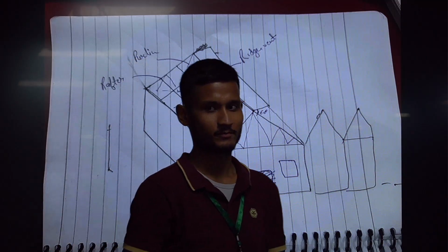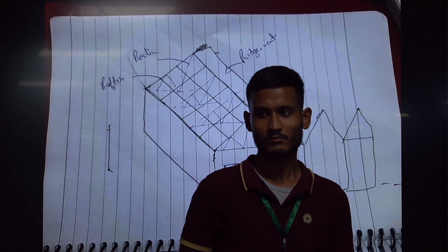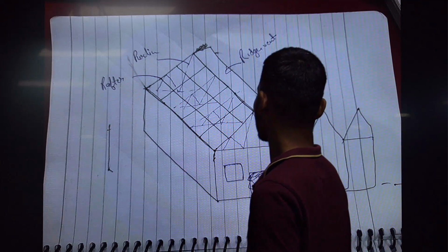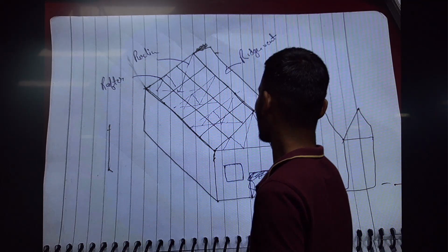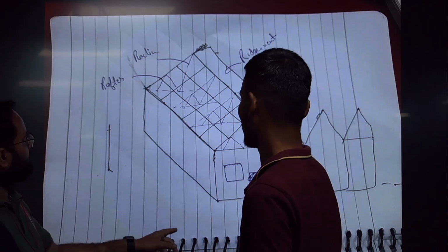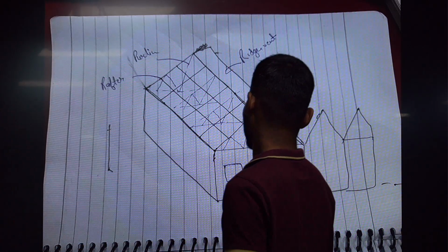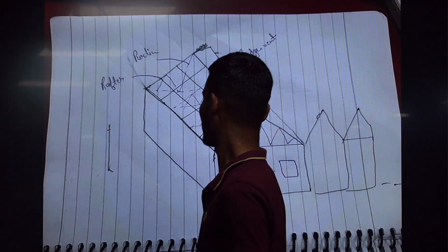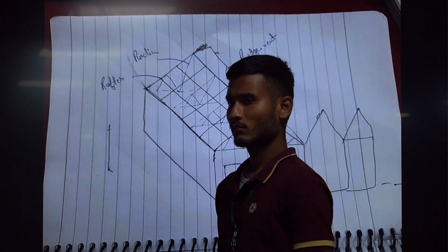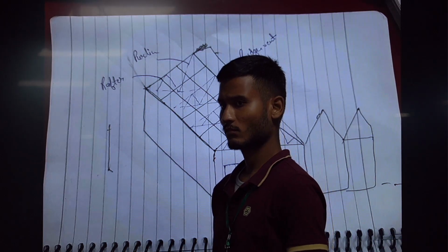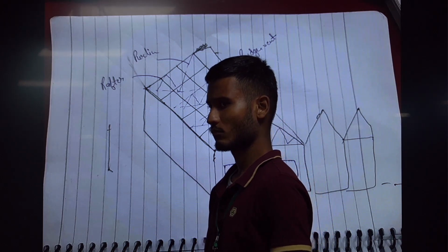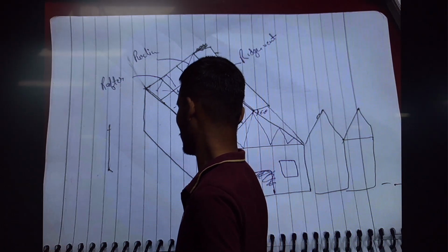Any questions? If it is a Venlo-scale greenhouse, that type of trusses you have is not correct. You normally go for a Warren truss. Remember the Warren truss? It's like two lines and then you simply go with it. Check the figure I've shown you. This is more for a gable style greenhouse with a high profile roof. When the roof is of high profile, you use this type of truss. But if it is a low profile like the Venlo style that you want for tomatoes, it should be a Warren truss, slightly different. So go back and look at the Warren truss picture that I've shown you, and you will see what I'm saying.